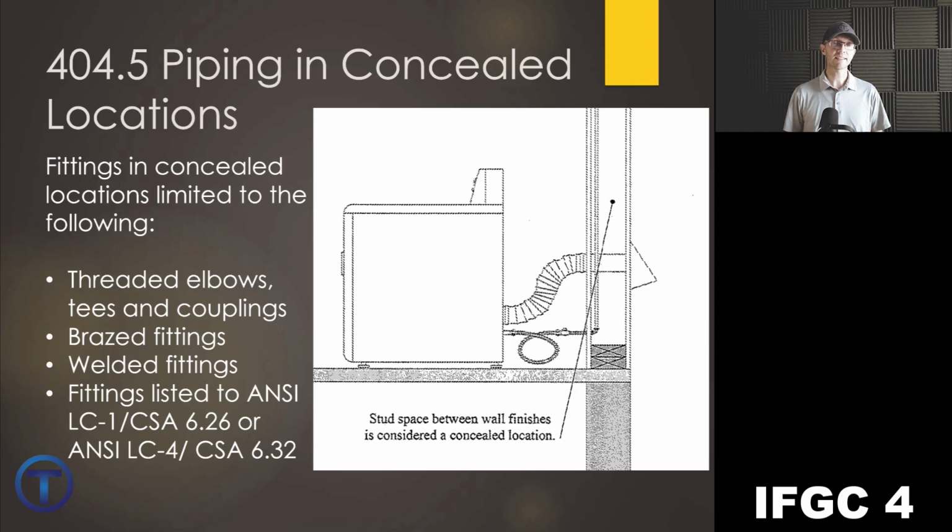404.5, piping in concealed locations. Here's the question. Is it okay for you to have pipes in a wall, buried in a ceiling? Yeah. It says fittings in concealed locations are going to be limited to the following. So if I'm going to run pipe through structure, through joists, through trusses, through walls, and that's going to get covered up later, some fittings are allowed to be used and some are not. The ones that are allowed to be used include threaded elbows, T's, and couplings. You can also use brazed fittings, welded fittings, and some that fit these other standards listed in this section.